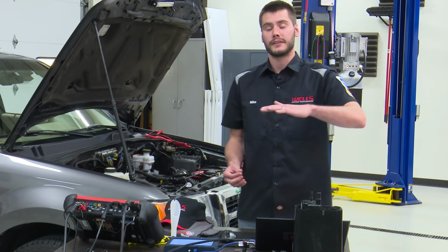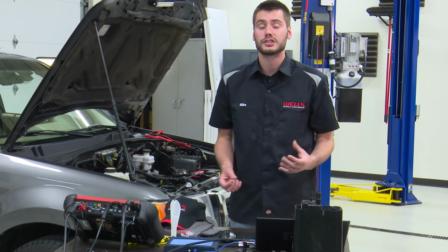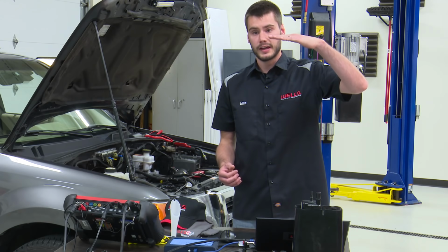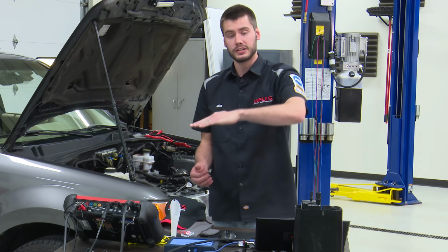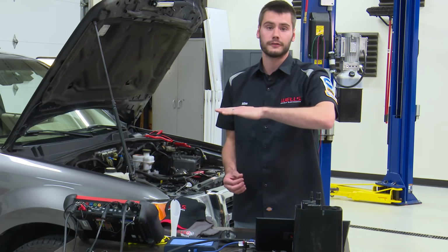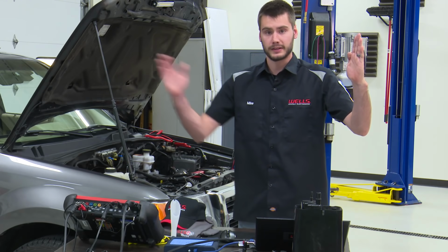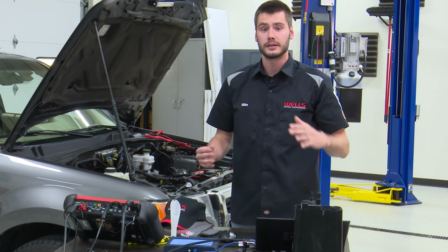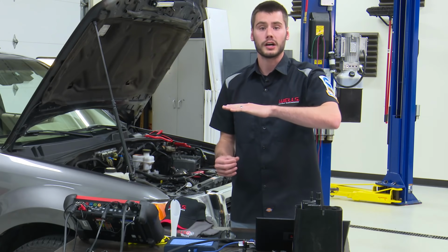We drop the vacuum below the threshold. So this vehicle, 8 inches of water. So here's our vacuum level. We come down, 8 inches of water. We fall below the threshold. We shut the front door. Okay, front door is closed, back door is closed. The entire system is sealed. We're below our threshold. Now we watch and we wait.